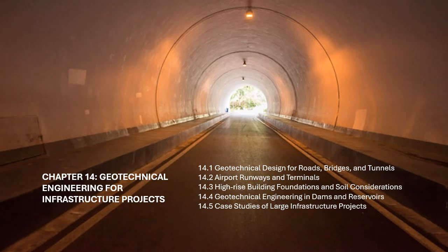14.3.3 Soil Behavior and Testing for High-Rise Foundations. The success of a foundation for a high-rise building depends on a thorough understanding of the soil's behavior under different loads. Geotechnical engineers conduct various soil tests to assess the soil's strength, compressibility, and overall behavior. Some of the most common tests include the standard penetration test, SPT.